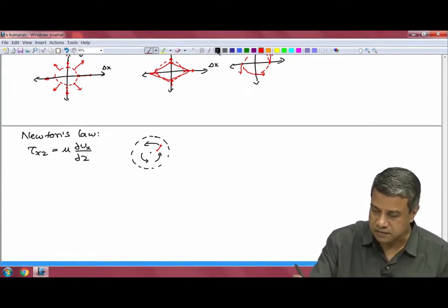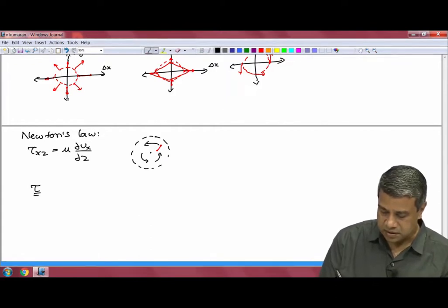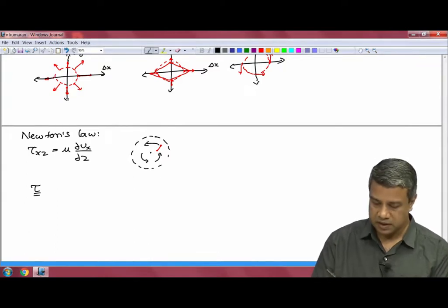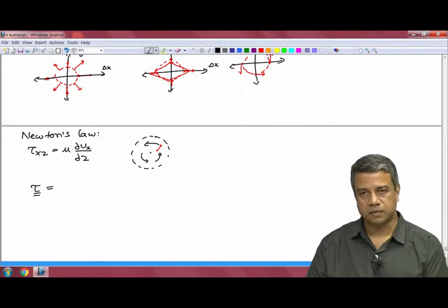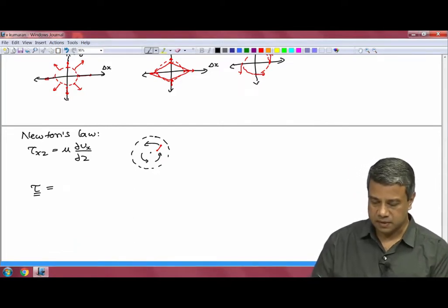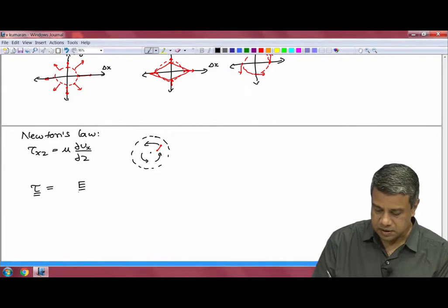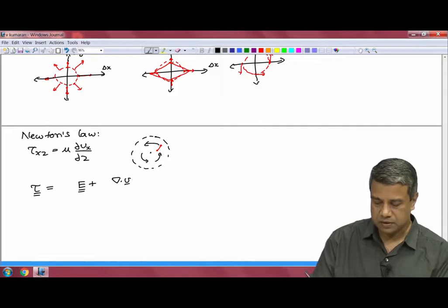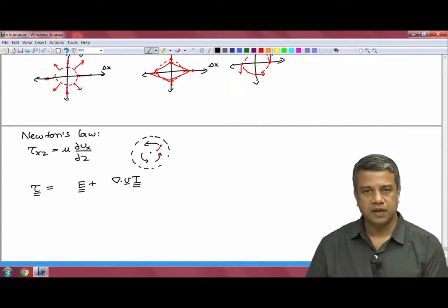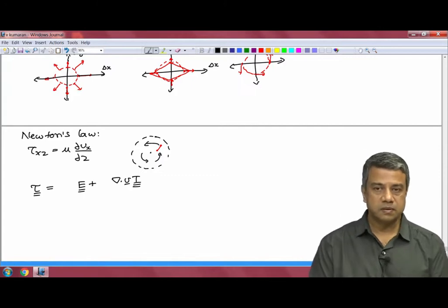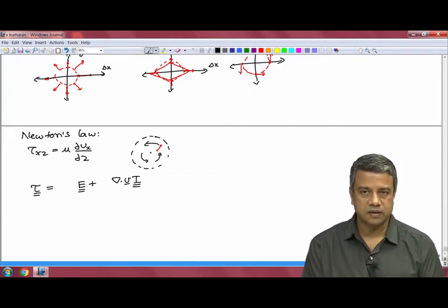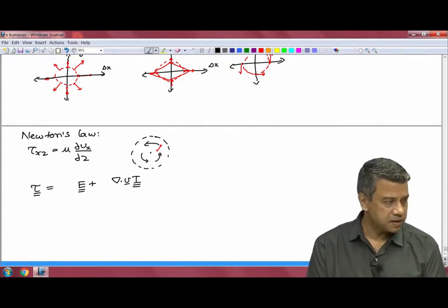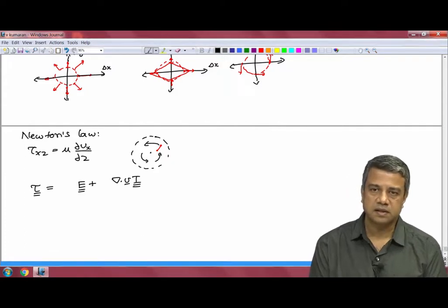Which means that the constitutive relation for the stress, this is the shear stress, recall, the total stress contains the pressure plus the shear stress, can have only two components. It has to be something times the symmetric traceless part plus some other thing times the isotropic part. Those are the only two possibilities for a relation between the stress tensor and the rate of deformation tensor. Not the components, but rather between the tensors themselves, because the constitutive relation is a relation between two tensors.